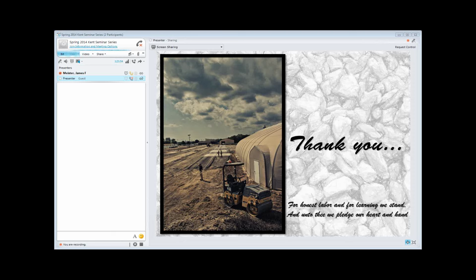Yes. When we go to the south sections, you see on the south side the additional 3 inches of the capping, which is actually now subbase. It becomes 6 inches of subbase on top of the subgrade. That's where we put the 4 inches of HMA, and that's where we did the FWD testing. And he had one slide showing the back-calculated layer moduli. Actually, some of those numbers matched with the LWD moduli you showed from individual layer testing. Subgrade and aggregate subgrade surface moduli were pretty close, of the pavement working platform models.